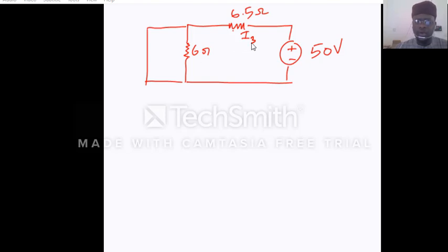So you make sure it remains the same. Now the current is coming from the 50 volt, the same as saying I3 is our maximum current coming from the power source. So it goes through, and then some portion of I3 will go through the 6 ohm, and then some will go through the non-resistor loop or non-resistor conductor, meaning we don't have potential difference. We can call it I1, which is the same as I3 minus I2, or I2 being removed from I3.